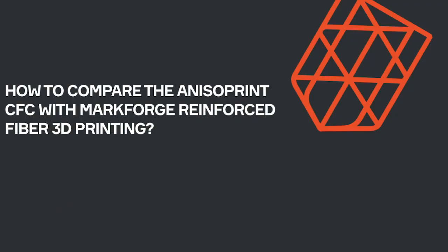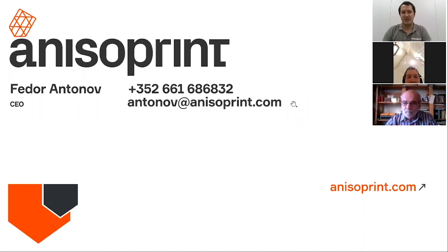How to compare the Anisoprint CCF with Markforged fiber 3D printing? It's simple. Markforged is prepreg based. Markforged pre-impregnates dry fibers, either carbon, Kevlar, or glass, with nylon, with a fiber volume fraction of about 28%, and then it's just simple material deposition where they melt the plastic inside the fiber tow and then place it.